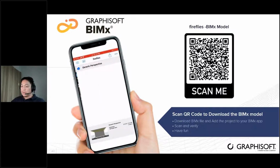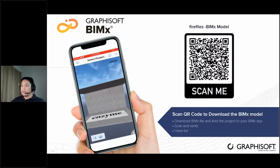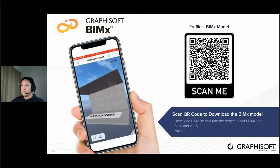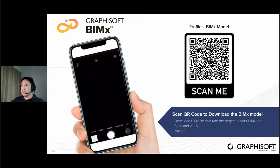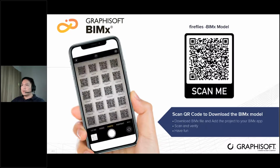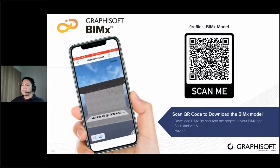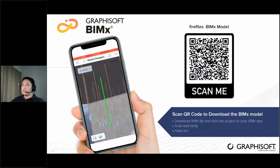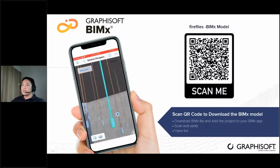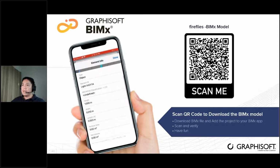Once we have this model, we can now try the QR code. The BIMx model transfer site is like a cloud service, where you could use the server space offered by Graphisoft, especially for SSA users. This is where you could upload or download a BIMx model to your phone or tablet. Once you have the model inside your BIMx, just go to your camera and scan the QR code. Then it will prompt you to open in the BIMx app.